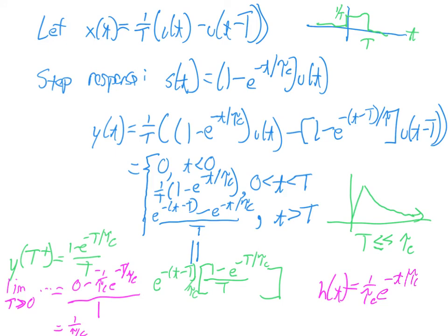And I need to multiply that whole function by the unit step, because when we started this we said this is the evaluation for small t greater than capital T, and we let the capital T go to 0. For small t less than 0, this rule still applies. So we zero out the function for t less than 0 by multiplying by u of t.